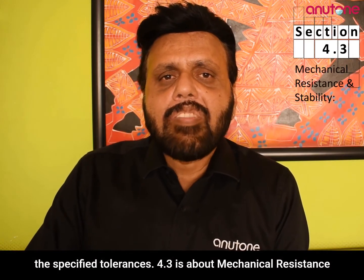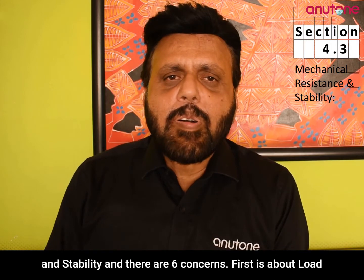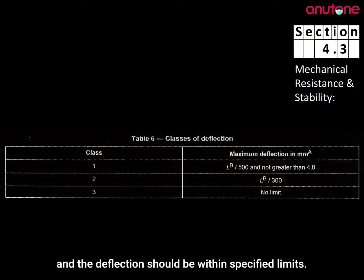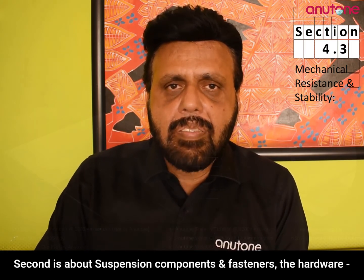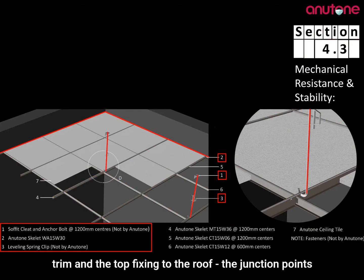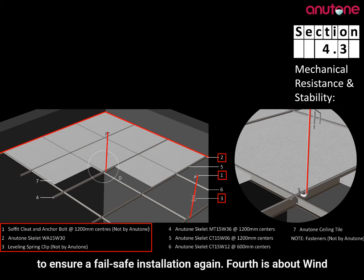4.3 is about mechanical resistance and stability, and there are 6 concerns. First is about load bearing performance, and the deflection should be within specified limits. Second is about suspension components and fasteners, the hardware, to ensure a fail-safe installation. Third is about perimeter trim and the top fixing to the roof, the junction points between the grid ceiling and the building elements, to ensure a fail-safe installation again.